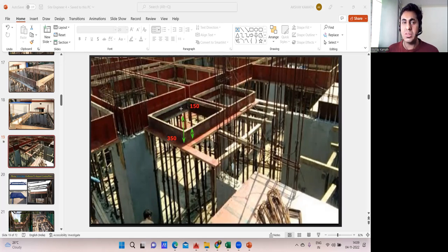This becomes inside shuttering, so this height will be the overall height. Overall height was how much? Depth of the beam 350 minus whatever slab thickness I need to deduct. Whatever answer I get, how much will I get? I'll get 200. So 200 will be the height of my inside shuttering. Getting my point? Practically the carpenter will cut a 200 board and then fix it.